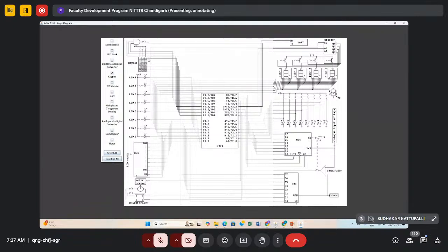So suppose we are getting 1 on this pin, which is pin number 3 basically. Suppose we'll just track it. Suppose I have pressed 1. So that subsequent pin will get logic level high. So this will tell our microcontroller that some button from this row is initialized. Now which button? So 3 lines are there in this.